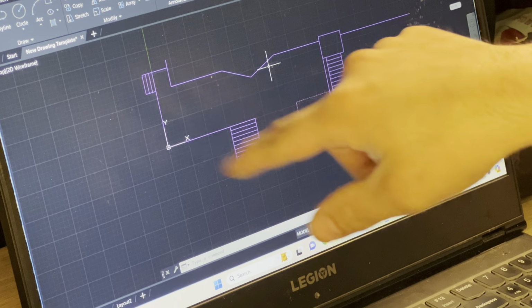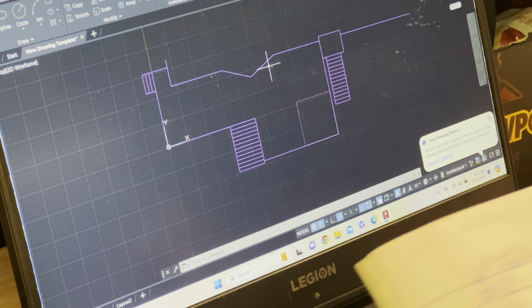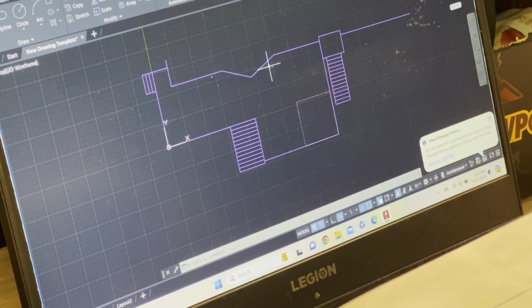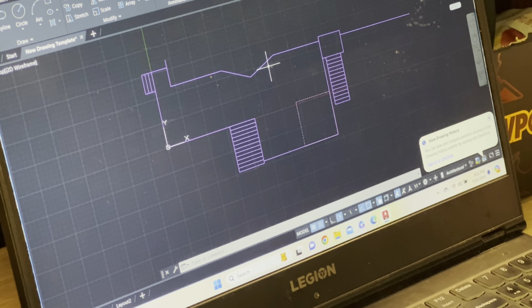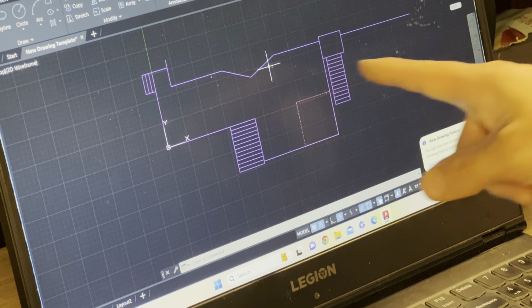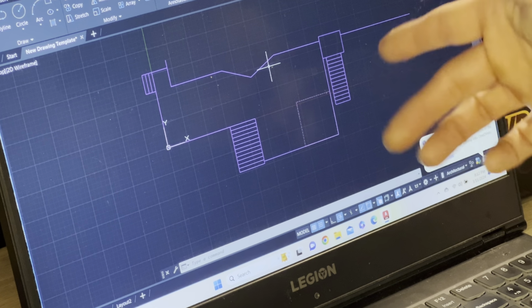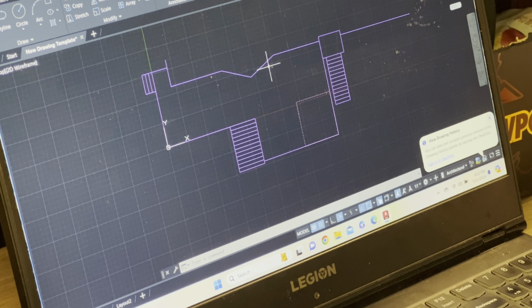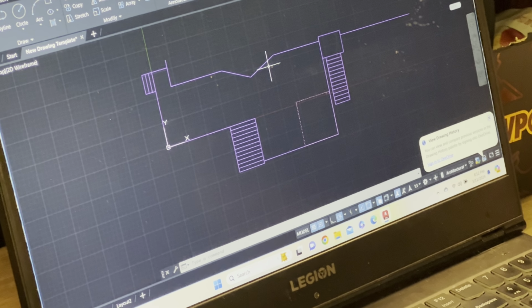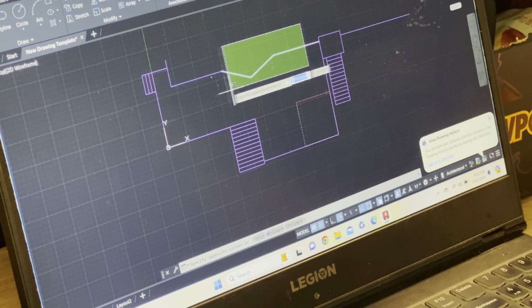I'm actually going to shrink this deck a little bit though, because the numbers that we actually pulled are 21 foot 5, but I would rather go 20 foot 5 to save on materials, and to save from having to splice the middle of this deck, right? Because our longest joist in pressure treated lumber is only going to come at 20 feet. So we're just going to max it out for the lumber that we're using, which is 2 by 10 lumber, right? So because I want to do that, I can grab all this stuff right here,